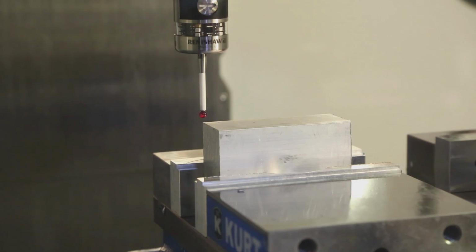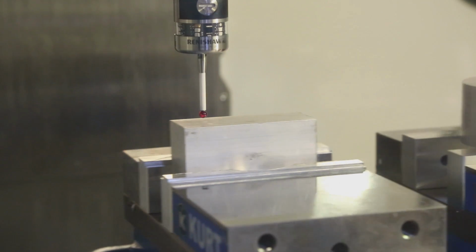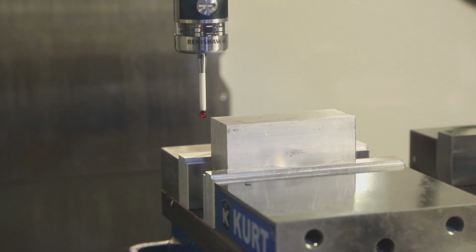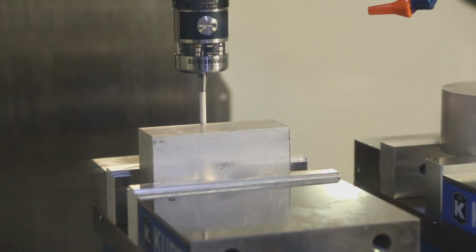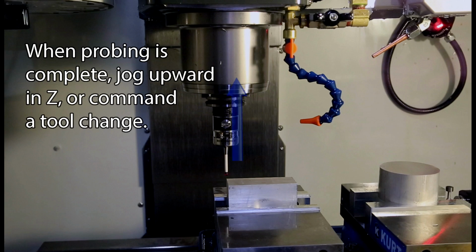Here's the routine running. Notice, the probe first moves to the center of the block, then probes the Z surface. It then probes the center of each side and returns above the corner. When probing is complete, jog upward in Z or command a tool change.